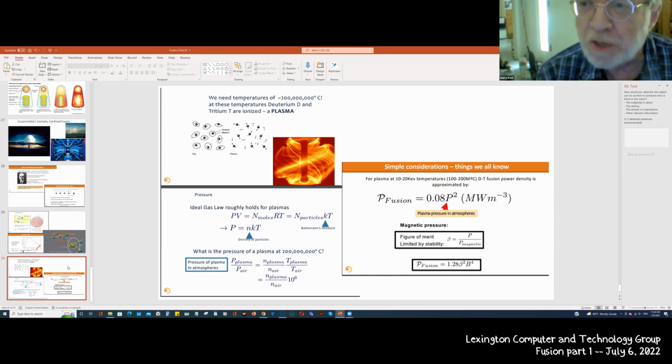If you assume that there's no AC riding on top of the DC, telephones wouldn't work. In your classical analog telephone, the energy you care about is the AC, the voice signal in the case of a telephone, and you get that out of variable resistance.